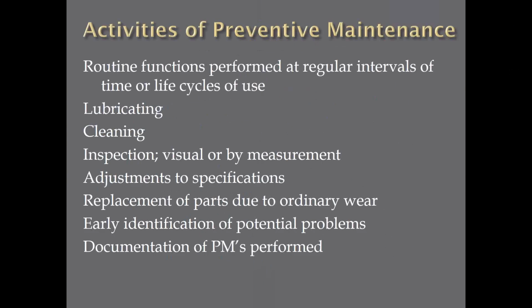But here's activities of PMs. I put some of these in here so you can train your maintenance people with some of these slides. But activities of preventive maintenance: routine functions performed at regular intervals of time or life cycles. Lubricating is a good PM task. What about cleaning? A lot of times maintenance people say, well, it's not my job to clean, but sometimes you can't find failures without cleaning. So the operator or the maintenance person is going to have to do some cleaning to find the failures.